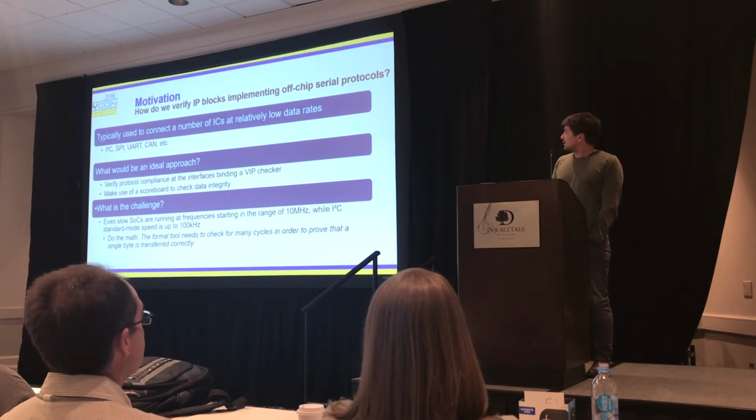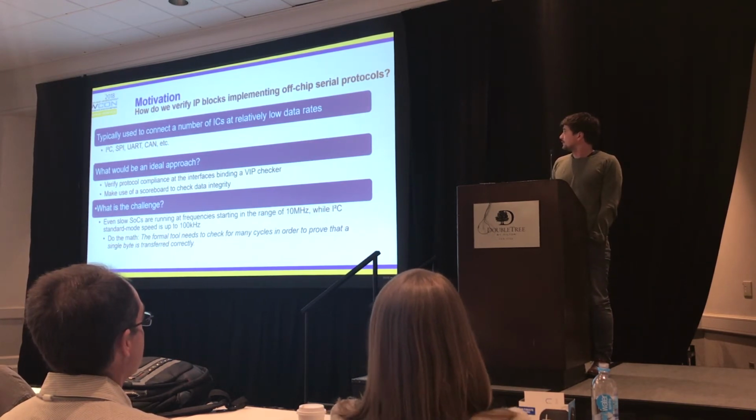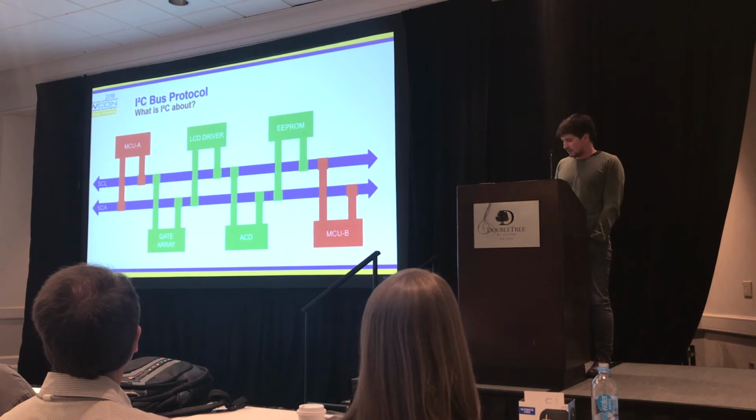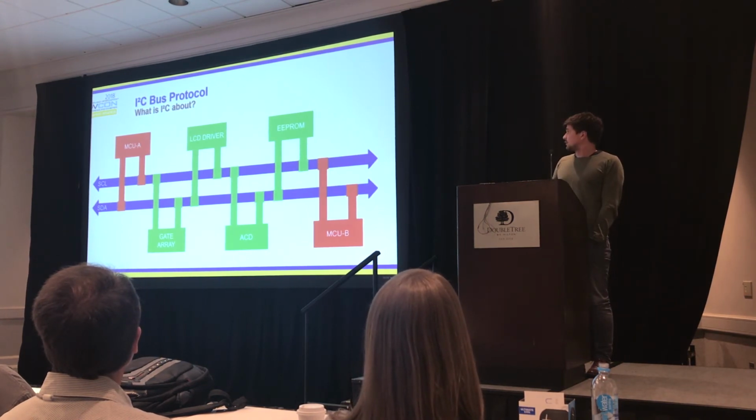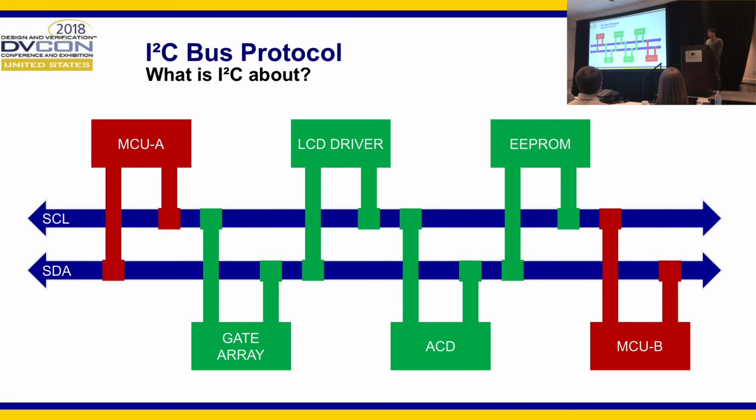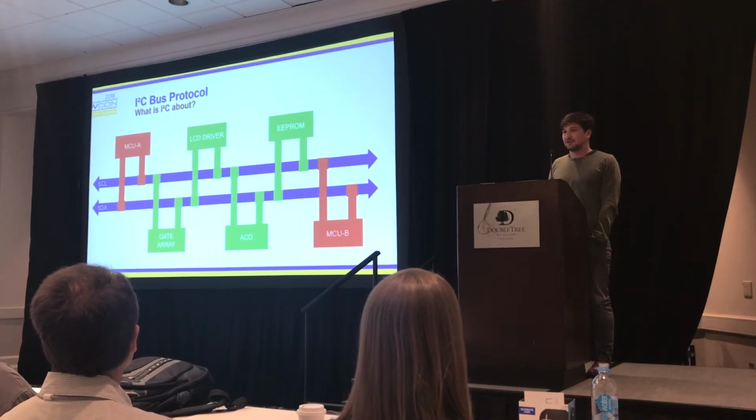So these were our two main goals for this case study, and I'm not going to talk a lot about I2C, just to introduce what it is in two lines. It's basically two lines to which the devices that present an I2C interface are connected, and at every point there is a master-slave relationship between them.